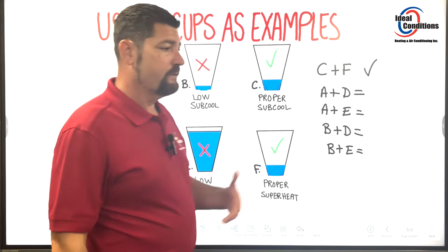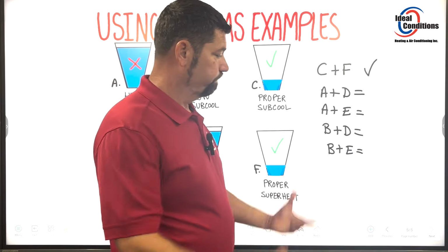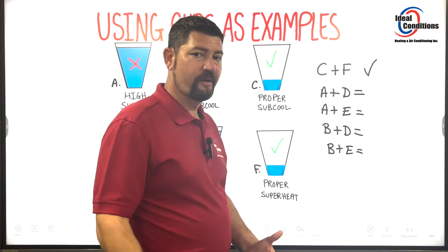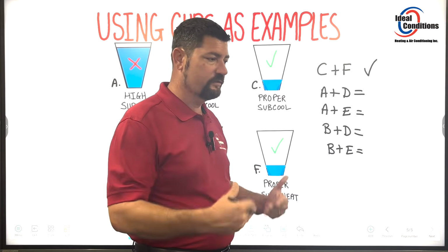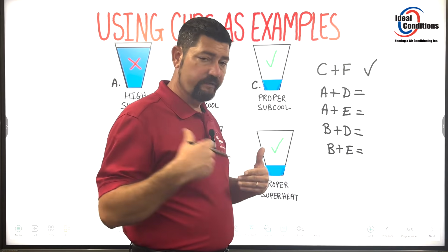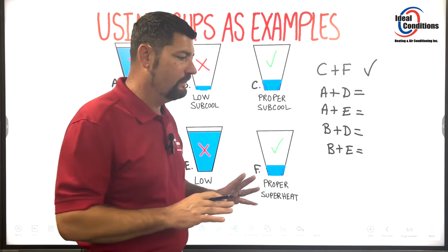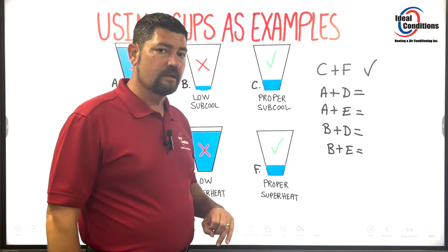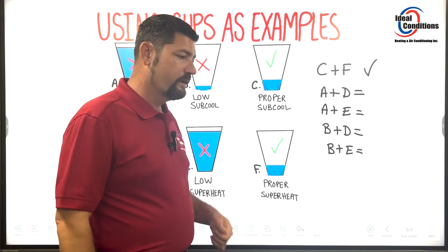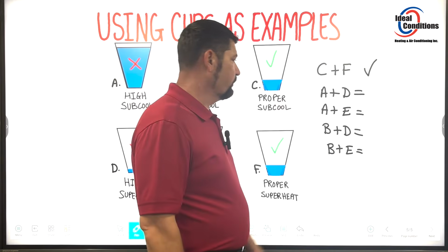How is a copper pipe going to just clog up? It's not like a golf ball's in there or something like that that can just clog it up. I mean, that doesn't happen. It's refrigerant. Nothing is going to be in there. You can have non-condensables, you can have moisture, you can have all those things that aren't supposed to be in there, but you're not going to have anything that's going to just clog something up. Screens can be clogged up, especially if you're brazing and you're not purging with nitrogen, that will create a problem.